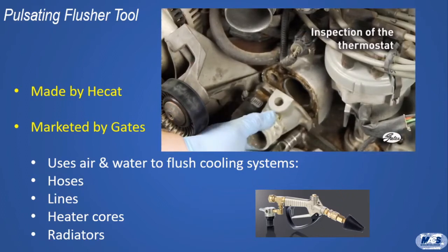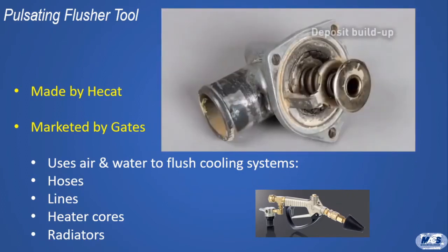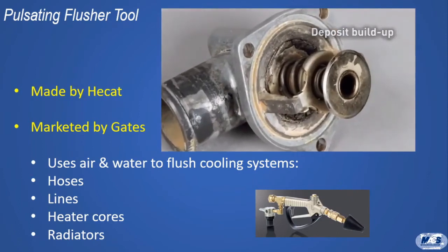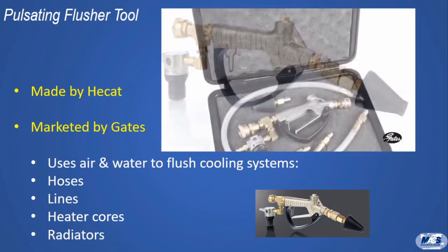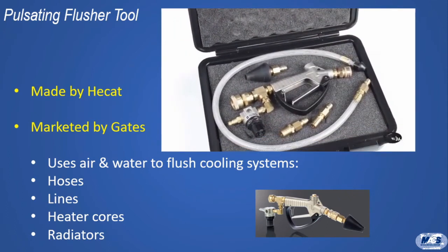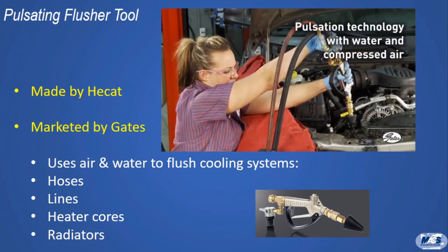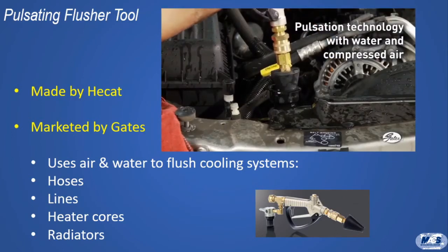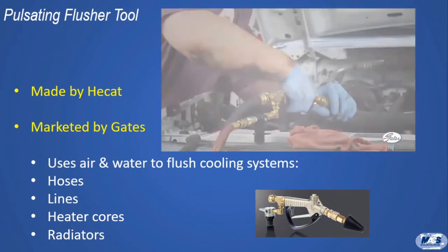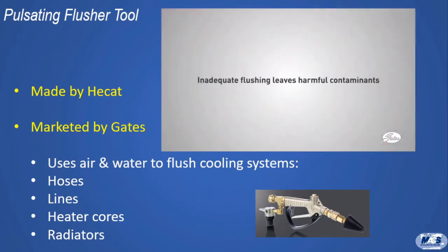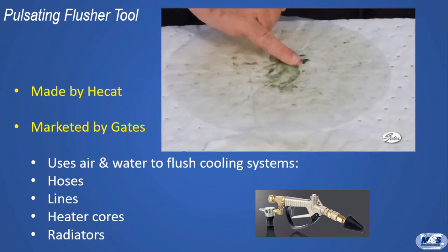But he had heard that plugged heaters, under some conditions, will show good flow, so he replaced the heater core. Once more, no fix. Actually, if there's good water flow through the heater, it's probably not plugged, although there are some rare exceptions when a section is blocked. And blowing shop air through the heater core can also be deceptive. Good airflow is not proof of a clear heater core.